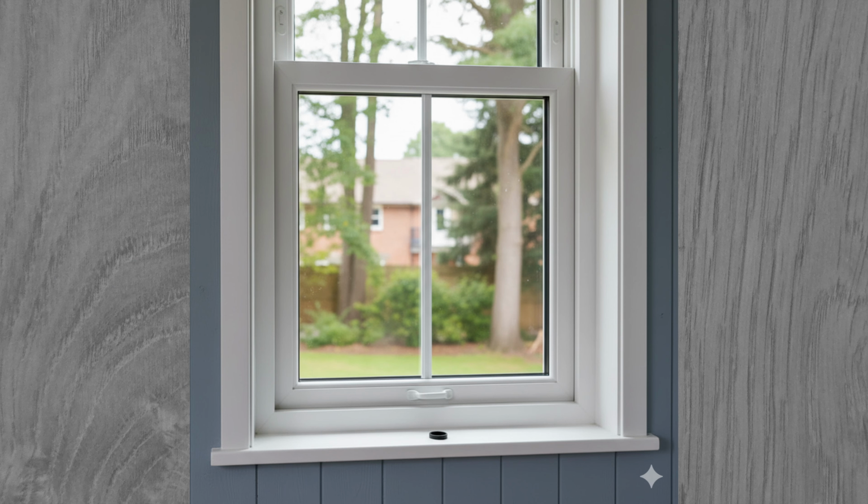Proper window design can help mitigate condensation issues. Using insulated window frames made of materials like vinyl and fiberglass provides better thermal insulation, reducing temperature differences that contribute to condensation. Installing window films adds an extra layer of insulation, helping to maintain a more consistent glass temperature. Additionally, maintaining airflow near windows by keeping curtains open and ensuring warm air circulates around them can prevent condensation buildup.